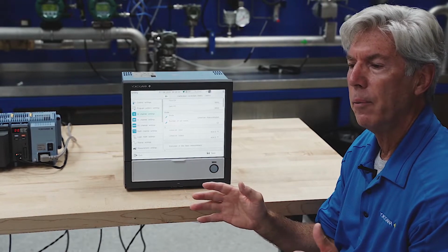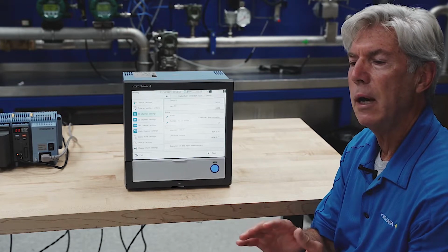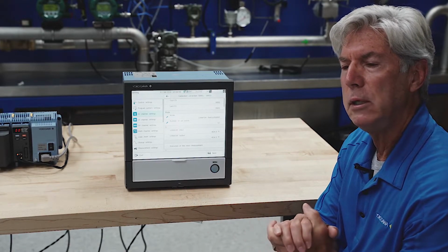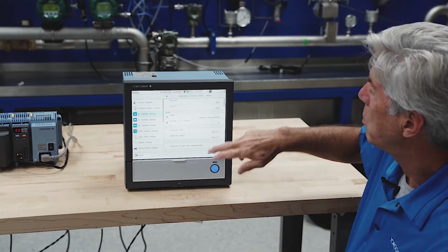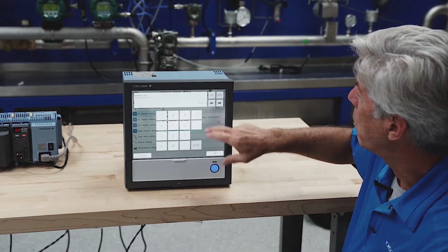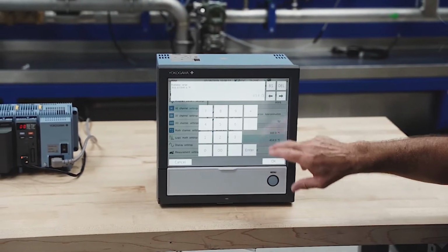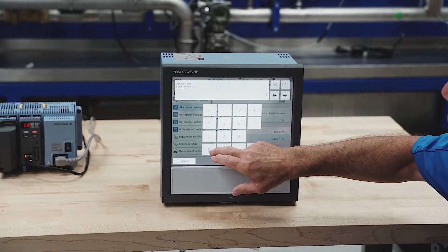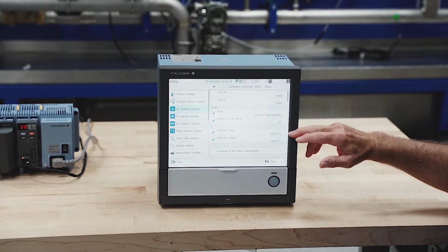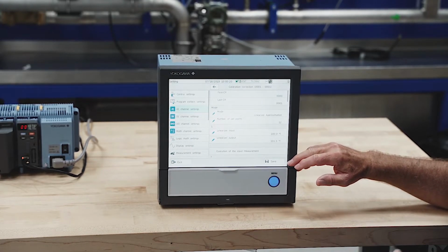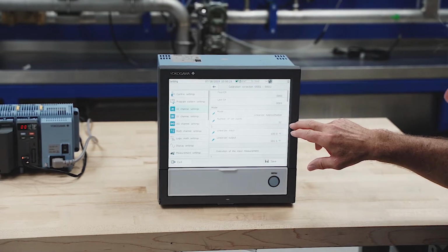So you might have a piece of paper for a particular piece of thermocouple wire that says every time that thermocouple wire sees 100 degrees Fahrenheit, it really should be seeing 101.5. So you can go in here and tell the recorder, every time that piece of thermocouple wire sees 100, you know that it really should be reading 101.5. So you can enter this in a lookup table for up to 12 points in the recorder and eliminate those known inaccuracies. It's a real nice feature.